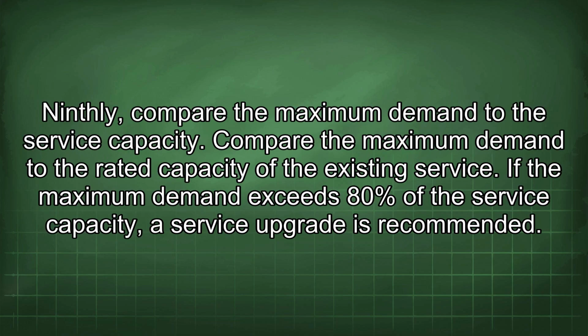Ninthly, compare the maximum demand to the service capacity. Compare the maximum demand to the rated capacity of the existing service. If the maximum demand exceeds 80% of the service capacity, a service upgrade is recommended.